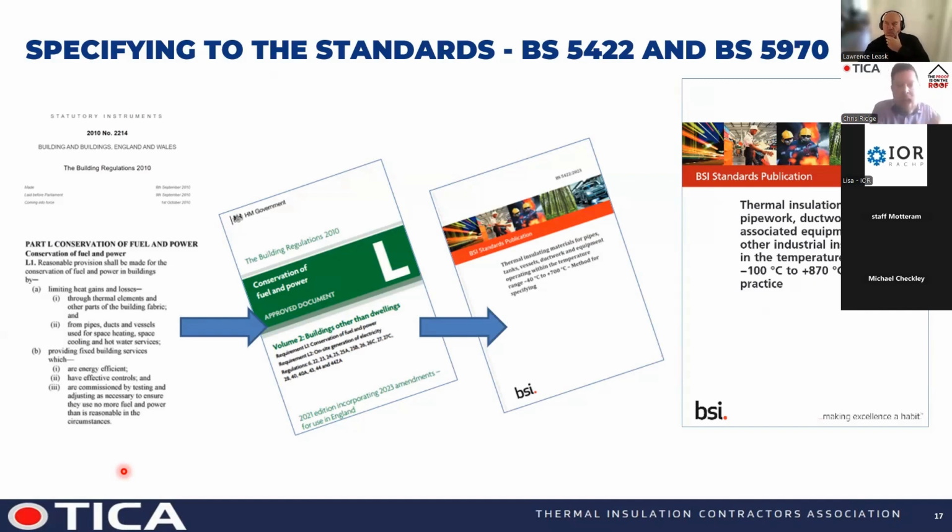And that does help you to meet the building regulations. So Part L, conservation of fuel and power, is then reflected. There's a means of achieving that through the approved documents, of course. So you have approved document L, both for dwellings, which is volume 1, and then non-dwellings, which is volume 2. They refer through to BS 5422. So all the tables in there are what really helps you to comply with what is necessary.